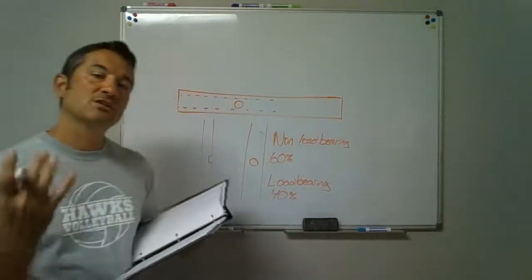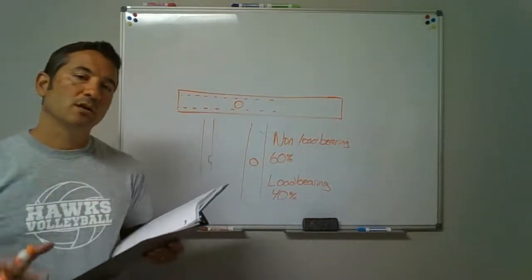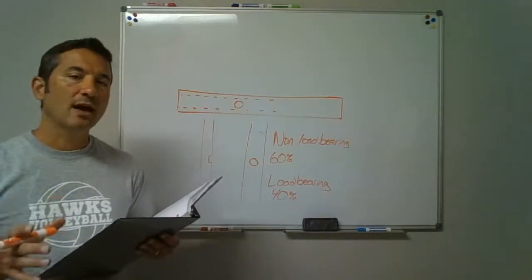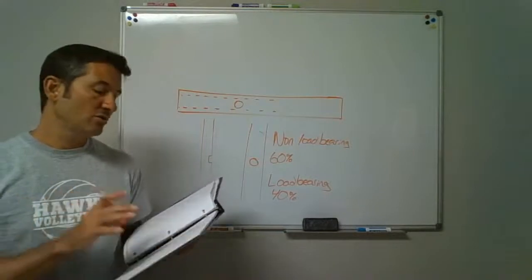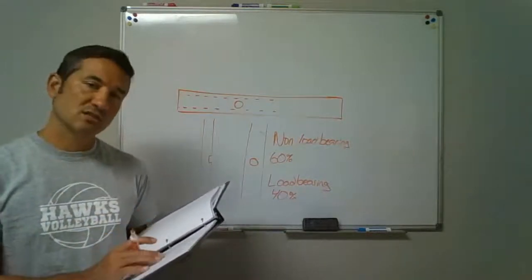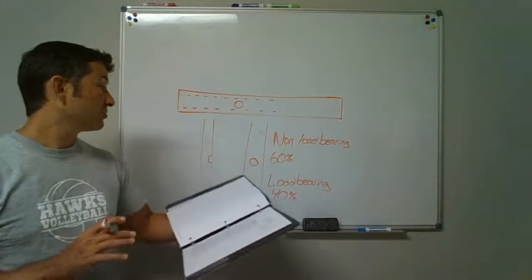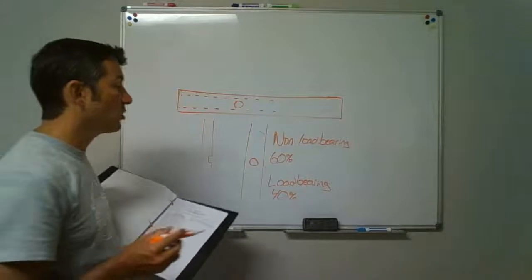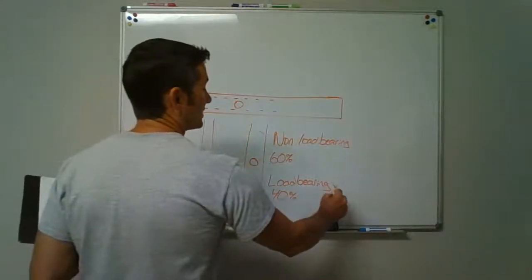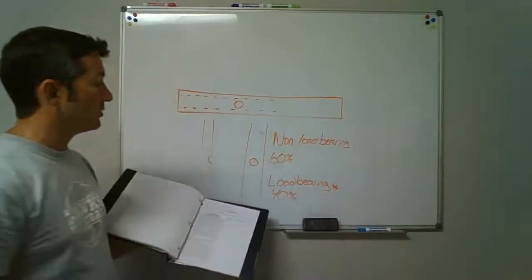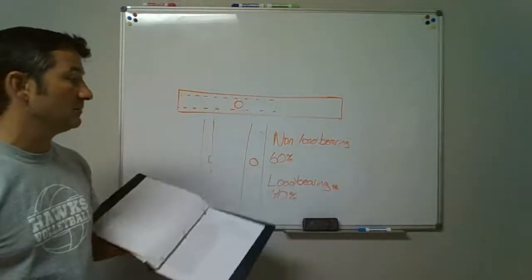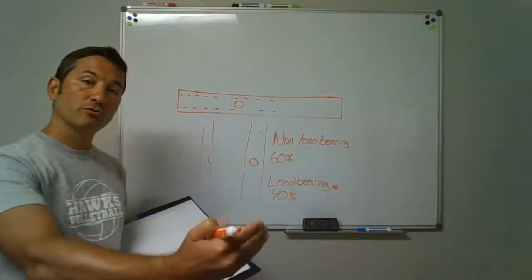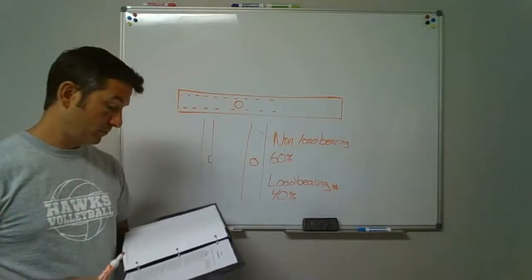Okay, and we'll talk more about this. We'll actually figure up percentages, because a percent doesn't tell me as much as a number. You know, give me a number. Tell me what that is, and we'll figure that up later. But just so that you know, this is the area that's talking about this. This has got some rules for it, that I just can't drill any size hole that I want to. We've got some percentages. This load bearing does have an exception to that. It will go on to say that you can go up to 60% as long as you double the stud and you don't drill through more than two studs in a row. Okay.